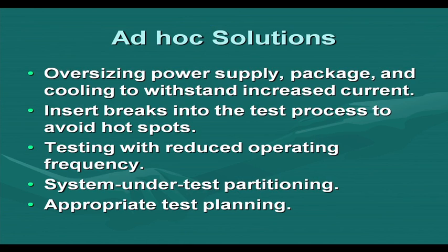Then for testing purposes, nobody is going to give us a packaging facility which is costly. And cooling is of course another problem. We cannot say that there will be a fan fitted, because this chip will become hot during testing. During test we want to cool it, so we will have some fan. So, that is not possible. So, this is one type of solution.